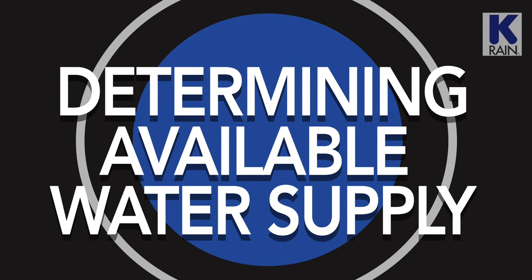The primary limitation on the design of an irrigation system is the maximum allowable flow rate. This determines how many sprinklers can operate at a single time, and will affect how the sprinklers are grouped into zones and how long those zones need to run.